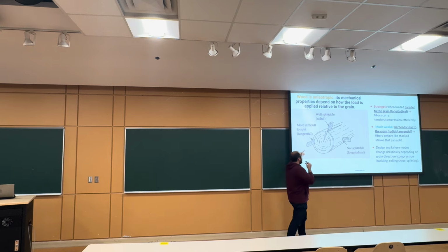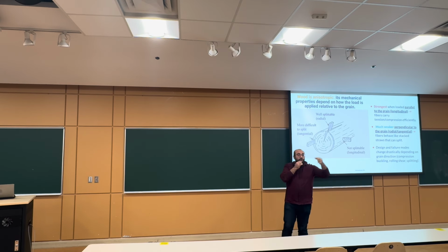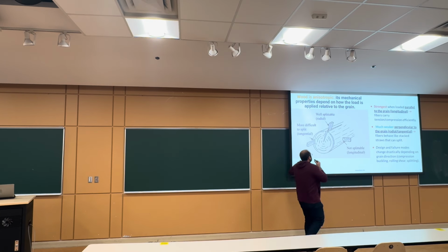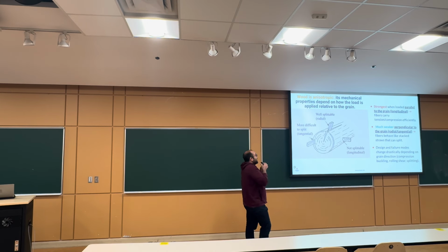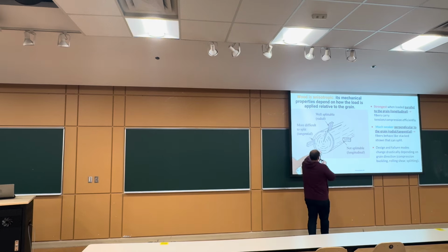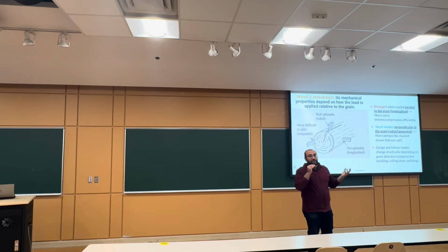Why? Because as the wood is growing in the outer direction, we can find that the wood is growing even on the micro scale, and those tubes that we found on the micro scale are growing into the depths of the material. So if we load the material in this direction, we are pressing over the cell walls of the wood, and thus we are gaining the highest resistance possible in the longitudinal direction, as the fibers in the cell wall are carrying the tension and the compression very efficiently and they are not splitting from each other.